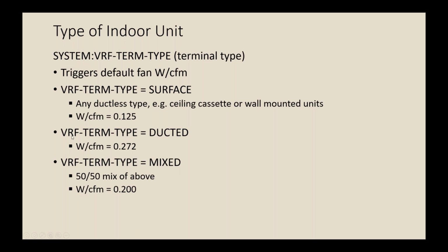And again, I think that's a reasonable value. If you have a ducted terminal type, the ducts have significant static pressure associated with them, and that will increase your fan power to the default of 0.272 watts per CFM. If you think you have about a 50-50 mix of ducted and surface mounted, then you can just describe it as mixed, and you'll get a value that's the average of the two above numbers.